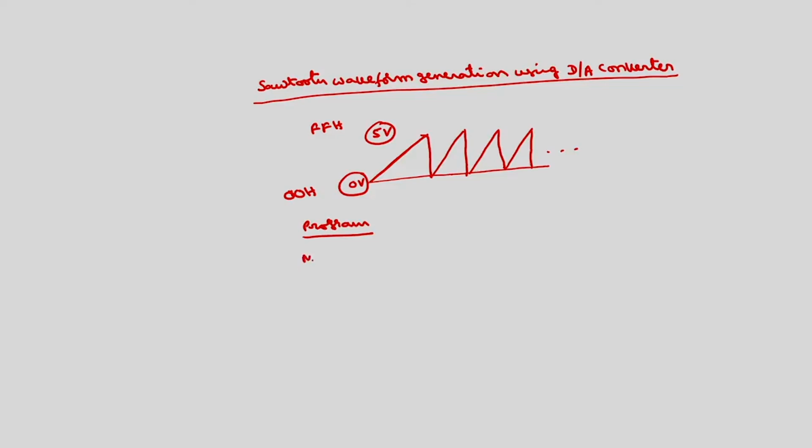you have to program port A as an output port. For that, move AL comma 80H, out FFH comma AL. This will program all the ports as output ports. Now I will take move AL comma 00, then I will output onto port A, whose address is FCH.